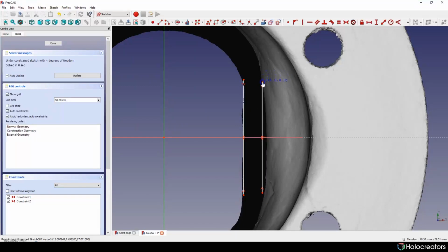Okay, looks like since we already add symmetry to these points, it's not gonna move anywhere. So basically I think we need them to be the same length, so we have to put equal constraint on them, and it works fine.